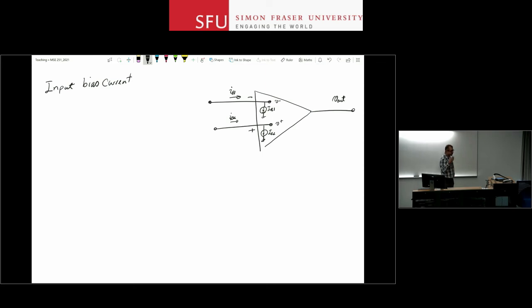I know these are the base currents, so a current source is maybe not really a good model. But if you look at these op-amps closely, IC is usually generated using a fixed current source. If your beta is fixed, your IB is going to be fixed. And therefore, a current source model for the input bias current is probably a good assumption.